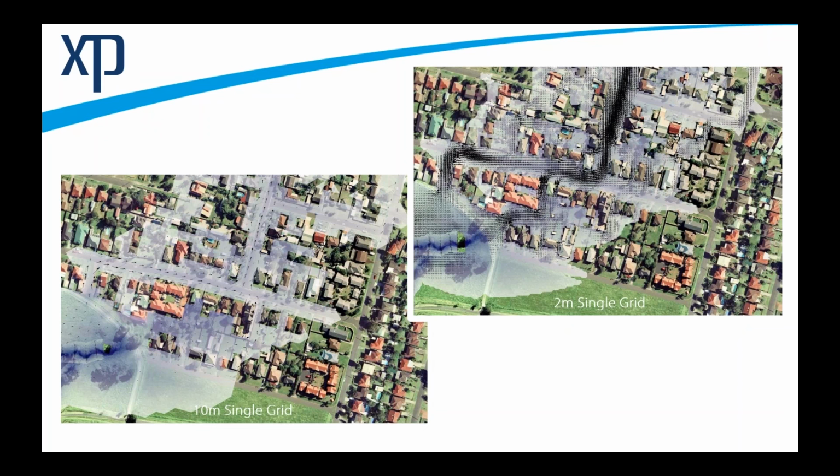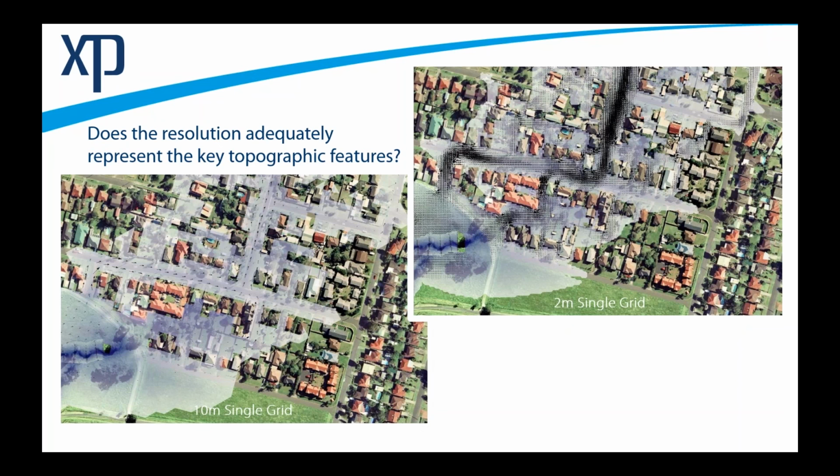So if you've got a road, what, 5 metres, 6 metres wide typically. If you want to capture that road, make sure your grid isn't above that, otherwise you're not going to capture the road curve. Exactly. You're going to miss it. So you just have to think about what you want in the model. You start big and run an analysis to see where the water's falling quickly, and then you can refine it later. Absolutely, yeah.